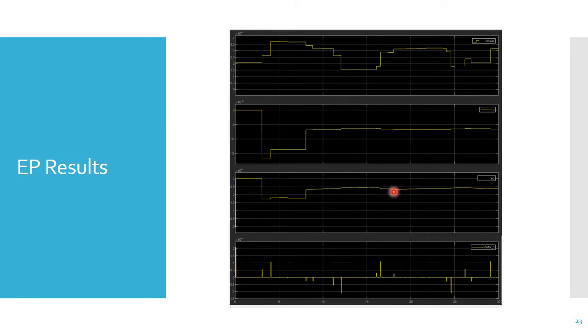And if we connect more devices, that means EP will start decreasing and allowing less power to be consumed. And if we disconnect loads, it will allow more power to be consumed back. And this EP value will be fed to the controller discussed previously to take the decision of how many devices should be disconnected and from which house.